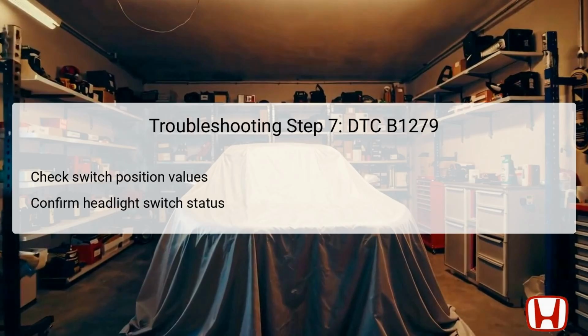If the readings correspond to the expected values while cycling through different switch positions, it indicates that the circuit is functioning as intended. Conversely, any discrepancies in the data list readings can highlight specific areas of failure, either within the switch itself or the associated wiring and control logic.